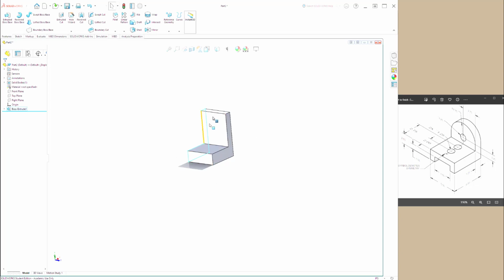We created the sketch, we created that. Let's talk about how to get this rounded top, or the arc across the top. The easiest way to do that is through the fillet command. And most people don't think about that. Most people would draw a circle and then trim half the circle off and then extrude half that circle. But realistically, what we did is we took the overall dimension and created that part, and now we can use the fillet command